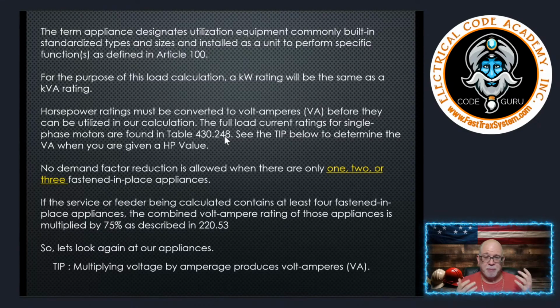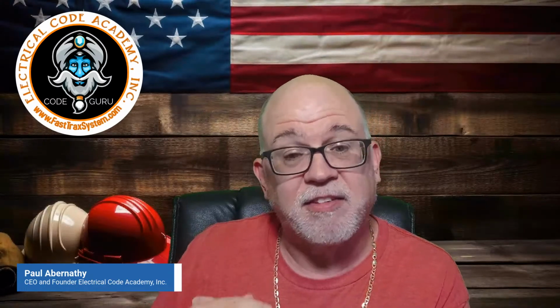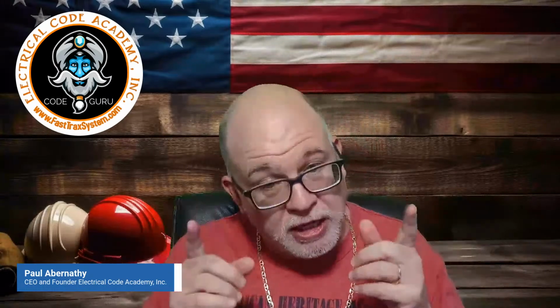People ask me that question all the time. Now, under the 2023 edition of the NEC, it doesn't have EV in the list in 220.53. So some people will argue that I can treat that as an appliance in order to have it count as part of my 4 or more appliances that are fastened in place. You need to work that out with your local AHJ, but I can tell you the intent was for it not to be.